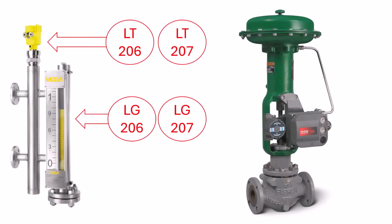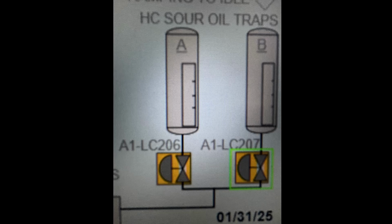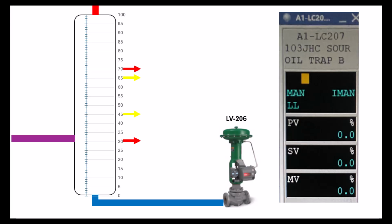The new guided wave radar level transmitter and digital controllers will allow this control loop to be run from the DCS. On the DCS, the graphics for the sour oil trap level controls will look like this. The faceplate for the actual level control valves will look like this. Let's go over how the controls will work to maintain the level of oil in the sour oil trap. They are set up a little different from the normal level control scheme.